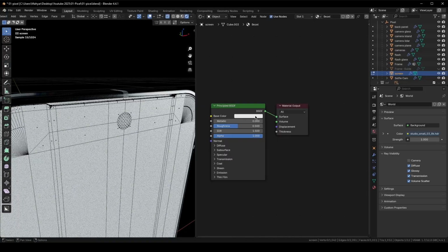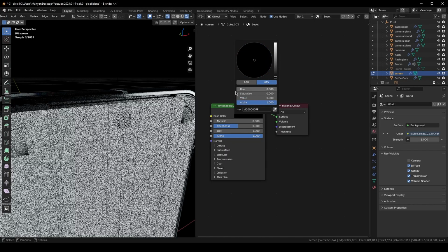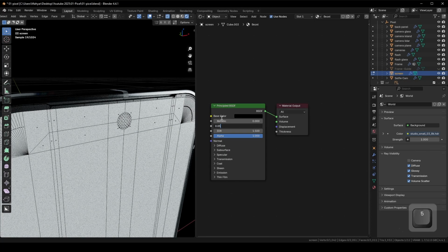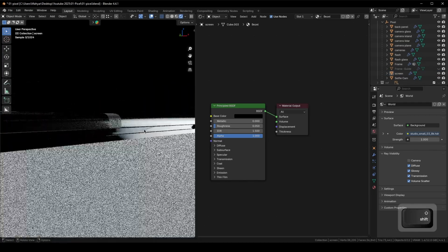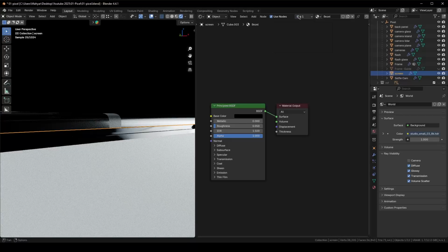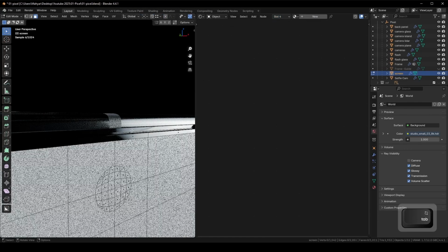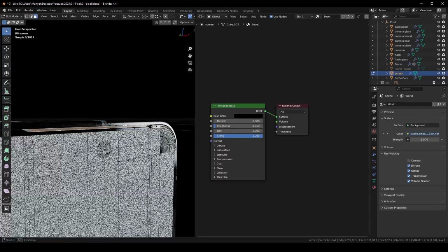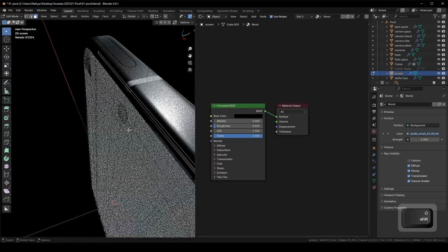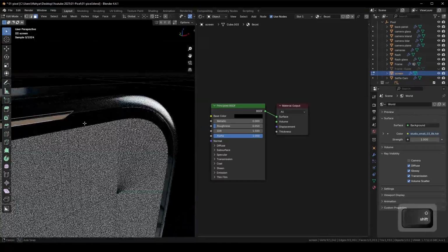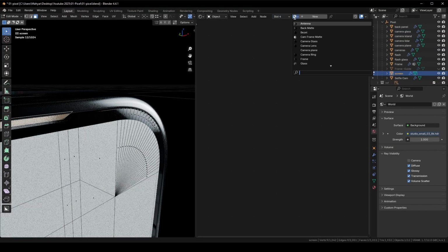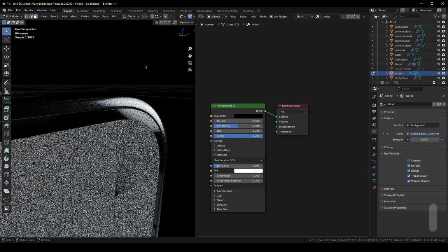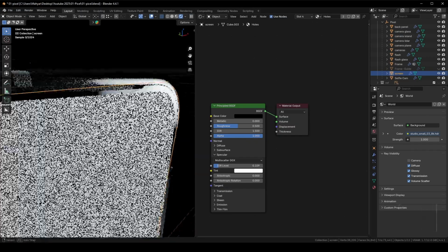For the bezel part, I create a shiny black material. And for this ear speaker part, I can create another slot. Press 3. Now I'm in the surface mode, and I can assign that to this slot and select holes and give the material of the holes to this part too.